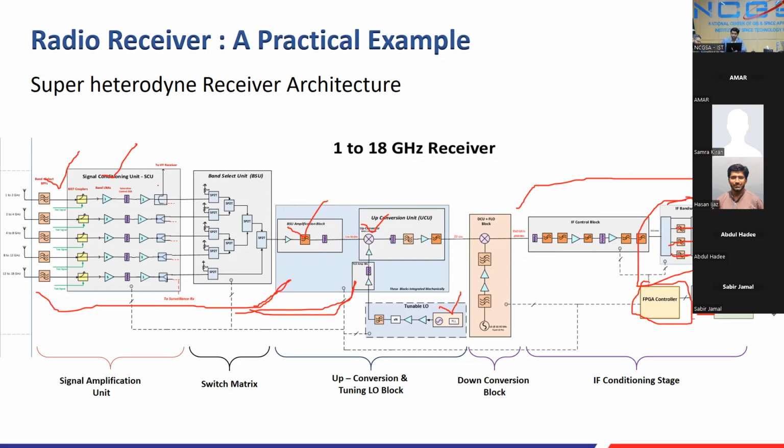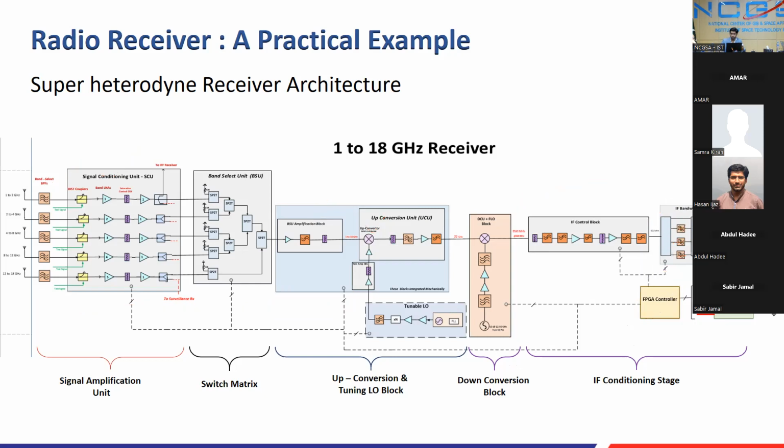So what this part does is it's a switchable filter bank. You have a 500 megahertz straight path, then 250 megahertz, 100 megahertz, 20 megahertz. You can lock at any frequency, go to a smaller bandwidth, go to a smaller KTB, and look further down into the noise floor. That is the application. This hardware has been fabricated and tested, and it's in field trials. Now we will move towards the software part, how we actually implemented that in our software.